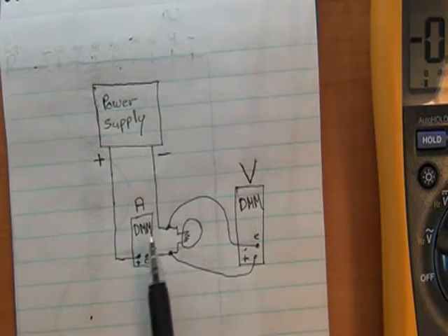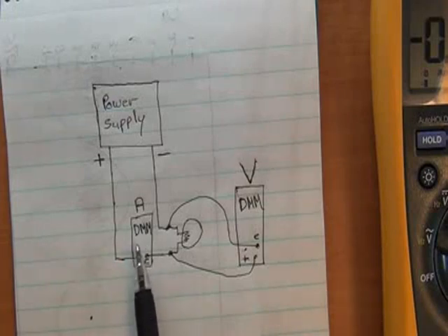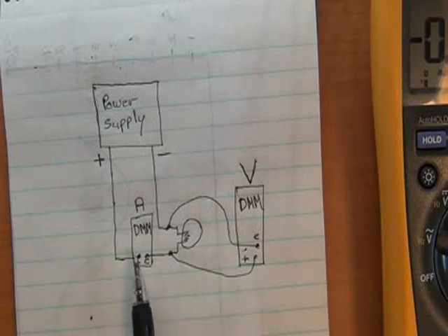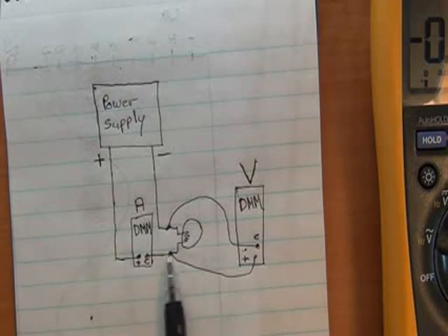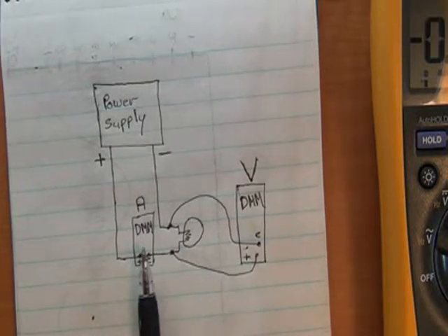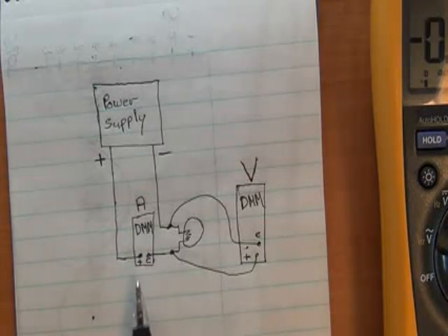Now we're going to learn about resistance and continuity probably in the next video, but that's the important thing to note when measuring current. If you don't do something more advanced like having a current tap, a current clamp or a shunt, the common way of measuring current is like we have it set up now, with all your current going through your multimeter. So that's the circuit. As you noted, we're measuring about 3 amps. Now we're going to measure something a little smaller to show how we can measure a smaller current, or amperage.